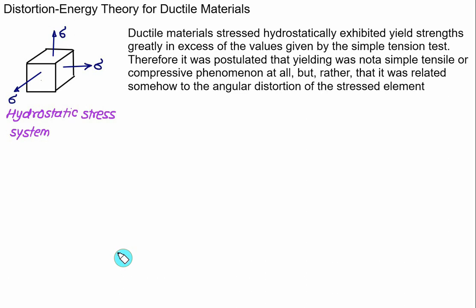One more theory we'll discuss is the distortion energy theory for ductile material. Now this theory is based on the distortion energy. Consider a hydrostatic stress system where three stresses, sigma, are acting in all three directions. When ductile materials are subjected to hydrostatic stress, that is, an even kind of stress on each face,